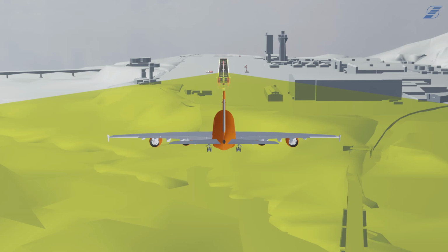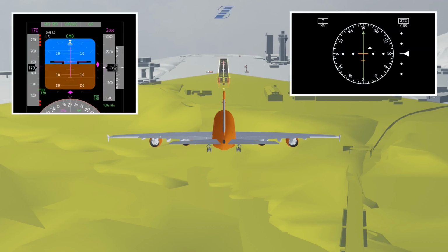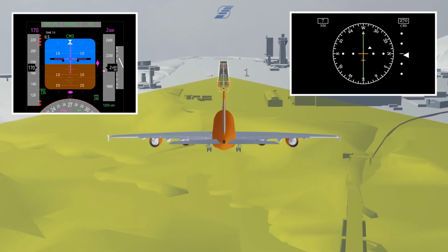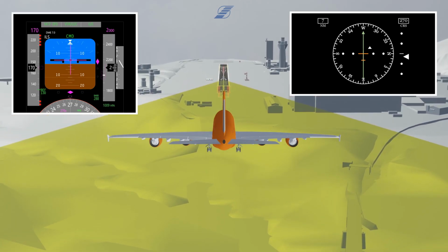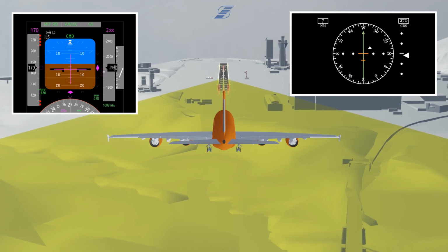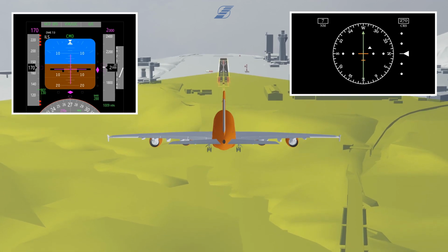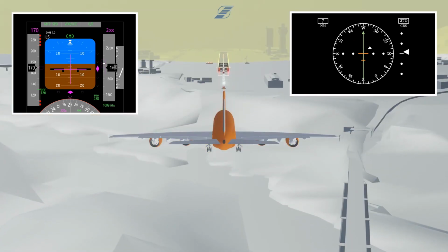Simulating that the displayed aircraft could move up and down on the spot, we want to look at what happens if it deflects from the ideal ILS guidance. That's why the instruments show an ascending flight, even if a pilot would just decrease the descent rate. The higher the aircraft flies above the ideal glide path, the greater the deflection on the scale next to the altitude display in the primary flight display, PFD, displayed top left. The horizontal situation indicator, HSI, displayed top right, displays this next to the course instrument.